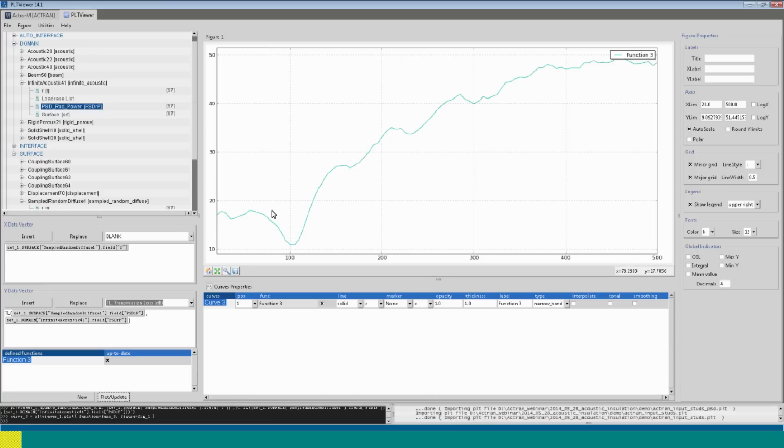So typically at lower frequencies, in the very low frequencies, the system is controlled by rigidity of the structure, and then we will have the first modes of the structure that are going to dip in this frequency. And then typically, if the problem has little damping, then we will have quite shaky curves, which is the zone controlled by the structure modes.